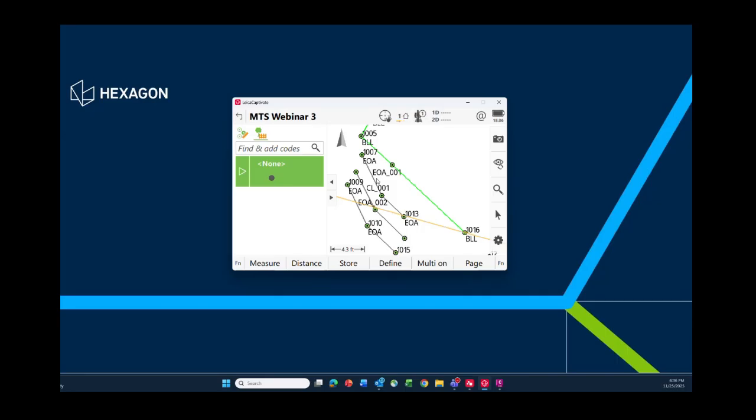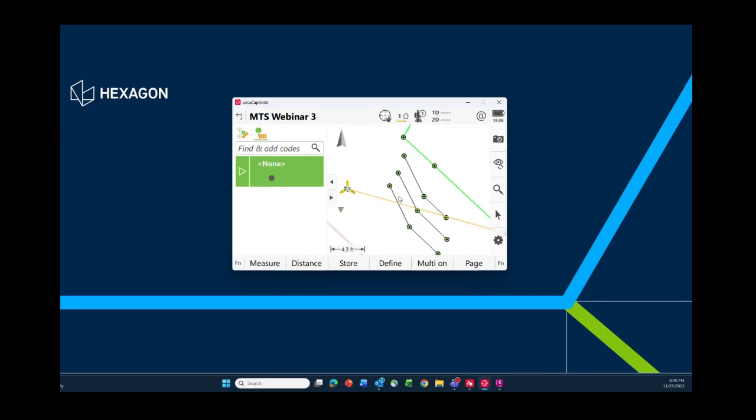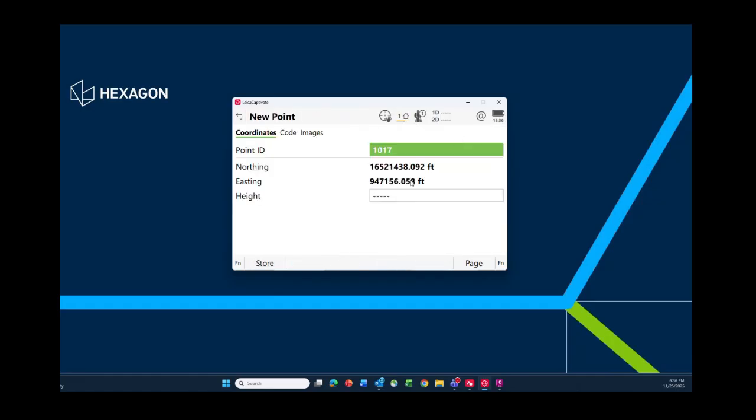So talking about those lines, the map view, what can you do for them on the map view itself? Few things, if you click anywhere and you hold a few seconds, you got the choice, you could manually create a point anywhere you want. So you'll get the coordinate of it. You'll need to guess the elevation. So you got the coordinate of where you click on the screen.